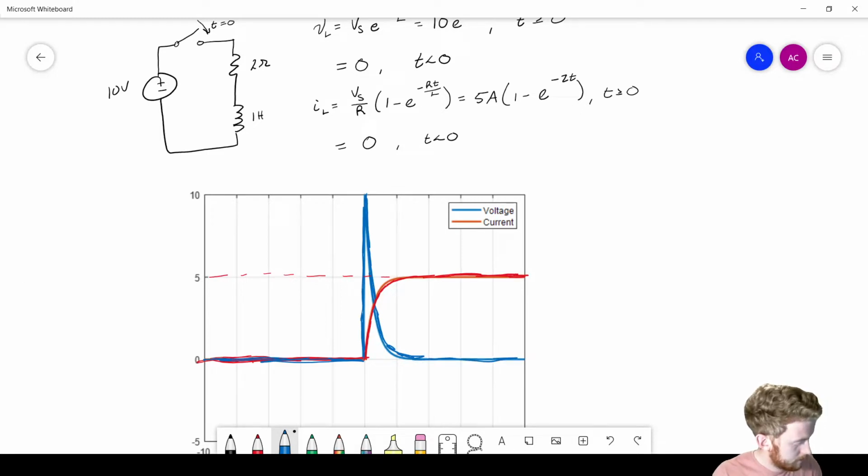So you'll notice if we just didn't have this inductor in this circuit at all, and I'll use the green color to show you the current, the current would just jump up, and it would look like this. Okay, so if you can see that green color, let me make it a little bit thicker. See, the current would normally just jump up and keep going. But when you add the inductor to the circuit, that's going to make it take a little bit of time to ramp up, okay, before it reaches that steady state value.